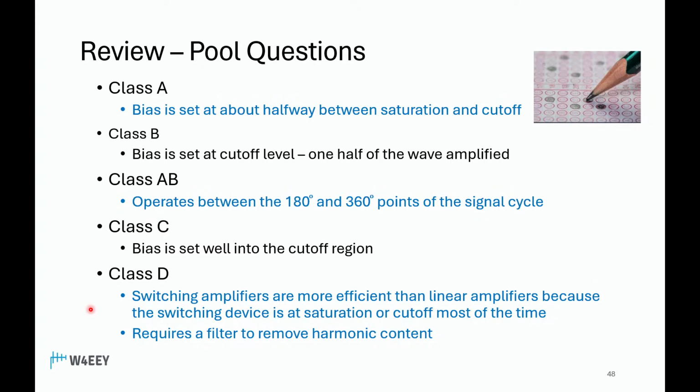Switching amplifiers are more efficient than linear amplifiers because the switching device is at saturation or cutoff most of the time, and it requires a filter to remove the harmonic output.